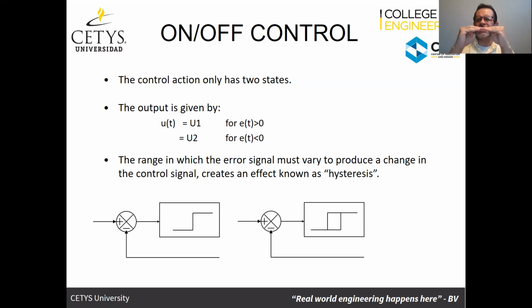So it's going to turn on at 79, and then it's going to stay on, and so things are going to get cold. Okay? The temperature is going to lower, and so when we go below the 79, it's not going to turn off. It's going to turn off when it reaches 78 or 77, depending on the threshold that we establish.